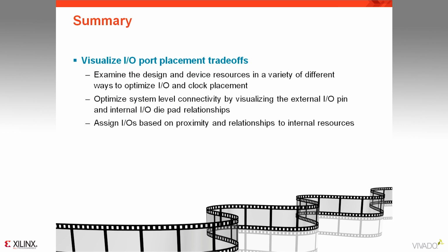So in summary, the Vivado Integrated Design Environment allows you to visually examine the device and design resources in a variety of different ways to optimize the I/O and clock placement. You can look at the overall system-level connectivity by visualizing both the external I/O pin connectivity as well as the internal I/O die pad relationships. You can examine the I/O proximity to the relationships of the internal resources such as the PCIe, gigabit transceivers, and other internal device resources.